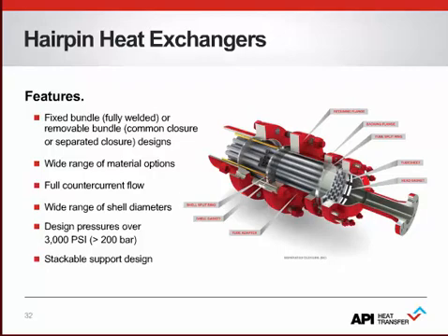Materials available are typical of a custom type shell and tube and can cover a wide range of fluid compatibilities. Shell diameters are typically in the standard pipe size range, but larger shells can be provided with customized closures. When larger shell diameters are needed, the processes typically don't require long lengths, so in these cases, a typical custom TEMA type might be suitable.